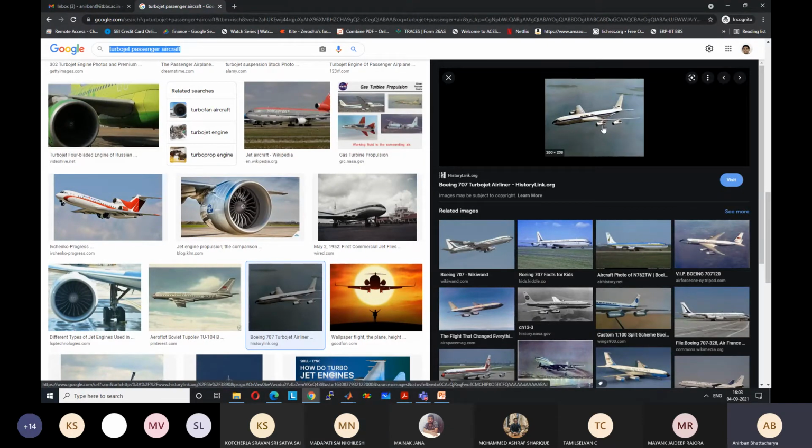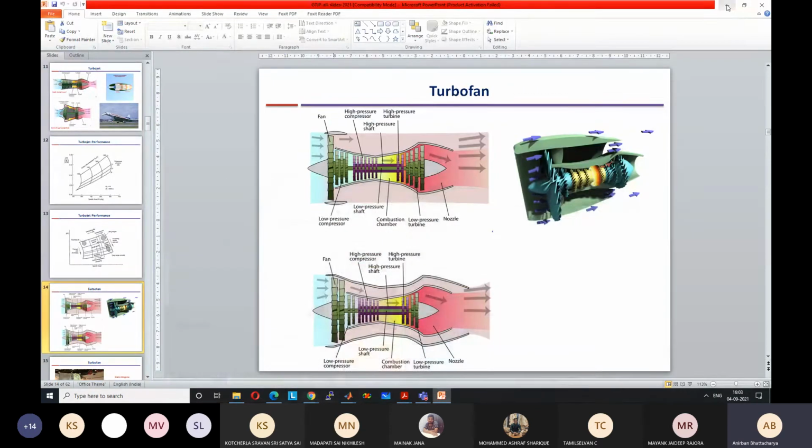It is a good point. So for these planes were designed, the 737 is an old plane, not the 737 Max. So generally the same design is used for many years. But what happens is that with time, engine efficiency increases because of better manufacturing processes. So you don't want to use the old engines. So you want to replace the engines. At one point of time, it was seen that instead of using turbojet, if we use turbofan engine, it will be much better.